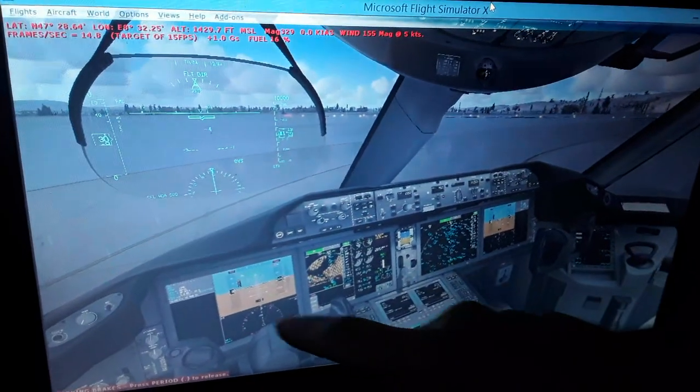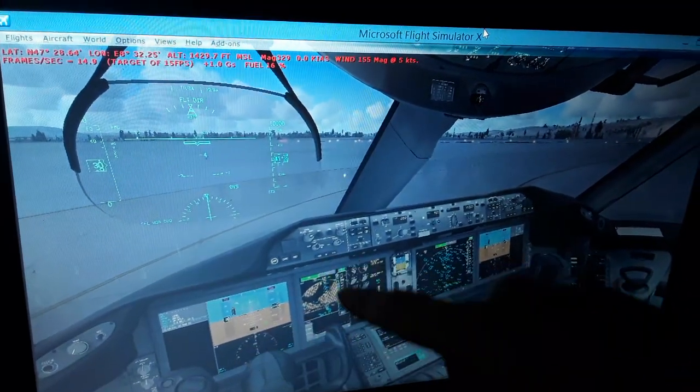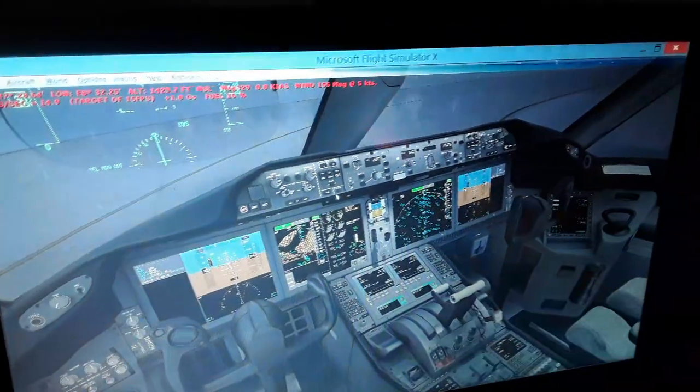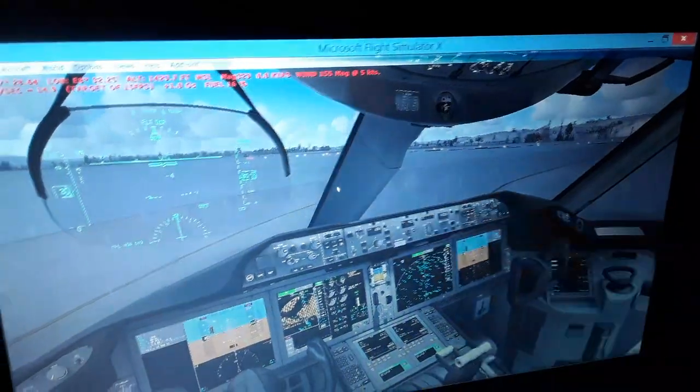We're going to create a flight plan, or a flight path or route, using the flight management computer. You're going to see it later. It's going to display both in the HSI here and in the horizontal and vertical profile of the navigation display. You will see the flight plan we create, and it's going to be followed by the autopilot flight director system panel. In flight, when we connect the autopilot, it's going to follow the flight plan we created, one waypoint after another. We have also the navigation display that displays the GPS position of the aircraft, the magnetic north pole and the geographic north pole, and the magnetic variation depending on where we are in the world.